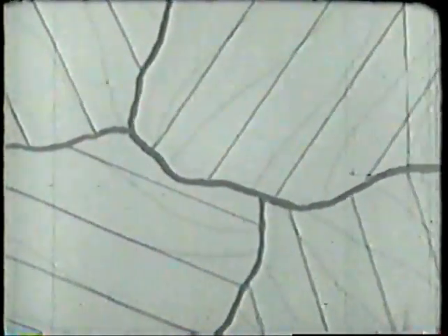Another theory, the fragmentation theory, states that during plastic deformation, minute crystal fragments break off and fall along the slip planes and grain boundaries. These fragments interfere mechanically with further slip by increasing the friction between crystal blocks and between grains. A third explanation, the lattice distortion theory, assumes that the crystal planes become bent and twisted during plastic deformation. The distortion of these planes, and also of the lattice structure at the grain boundaries, increases the resistance to further slip.